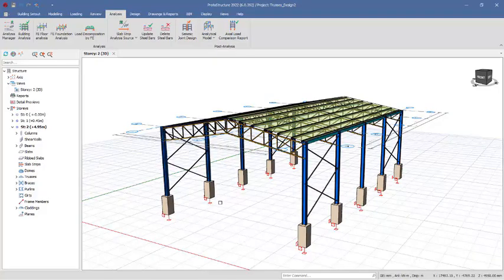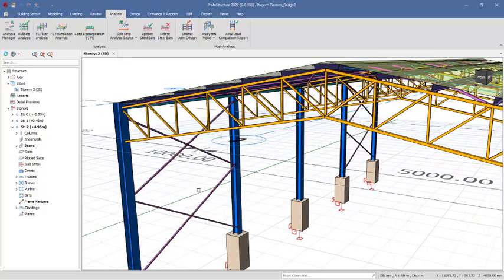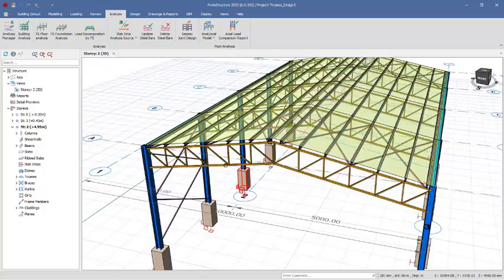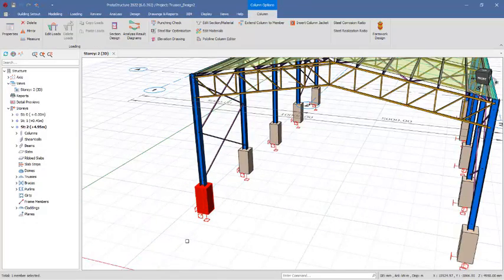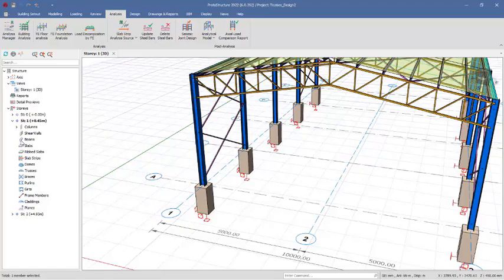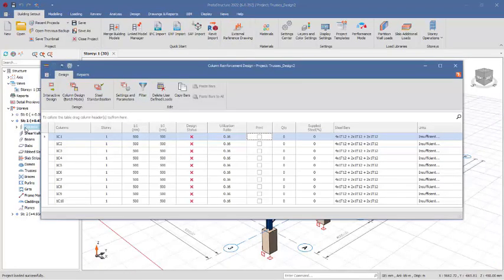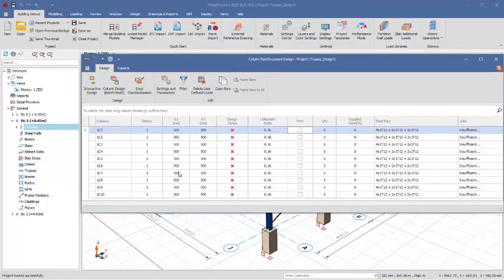Right. So at this time, we are going to be checking the structural elements to see if they have actually passed the design successfully. At first, we'll check the reinforced concrete member, which is the column right there. So you navigate to story one, because that is the story where we have the columns, and then select it, right click. So we will be considering the arrows. Selected the active story of the columns. You have this. So these are the RC column sections.